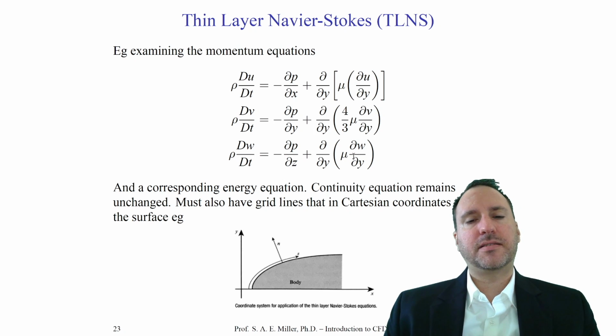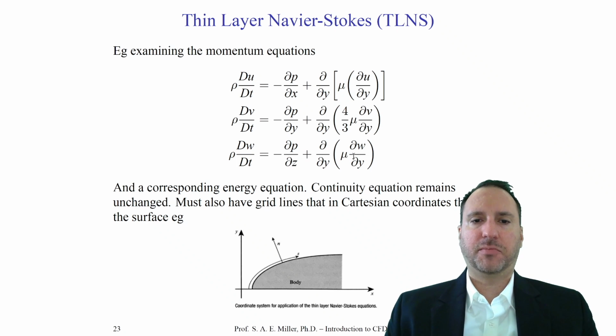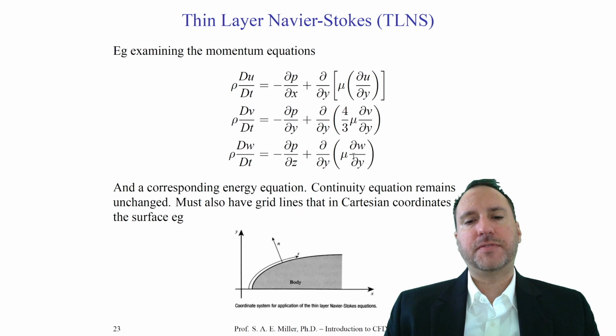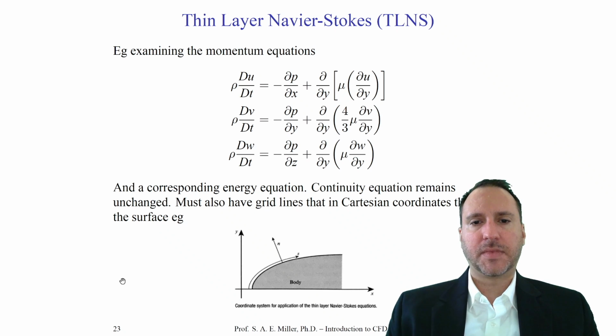So if we make these assumptions, we cannot hope to ever predict fully three-dimensional compressible turbulence. We are making assumptions about the flow and the turbulence itself, and might actually solve these equations in somewhat of a more steady state or a state with a turbulence model. Typically, these are solved with structured grids that conform to bodies.